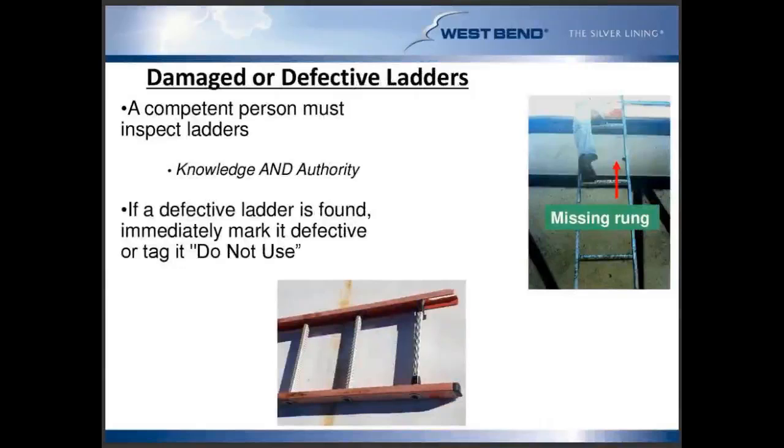So we talked about choosing the right type of ladder for the jobs we're performing. Now we need to make sure that we're not using ladders that could be damaged or missing parts. And obviously, if we do move forward with using one that is damaged, it could result in serious injury. So when looking at the OSHA requirements, they do talk about a competent person must inspect ladders. And if you're familiar with that term competent person, you might have seen it in different requirements from scaffolding to excavations. It's also used in the ladder requirements as well.